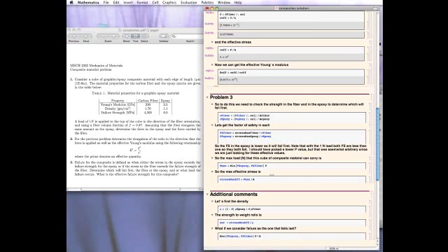We're going to take this kind of extreme one, that as soon as the epoxy starts to fail, we're going to call that failure. So this is a very conservative definition of failure for a composite. So to do that, we need to compute the stresses in the fiber and the epoxy and compare those to the maximum stresses allowable in the fiber and the epoxy. So basically what I'm doing here is computing a factor of safety in the fiber and a factor of safety in the epoxy for this 5 times 10 to the third Newton force.